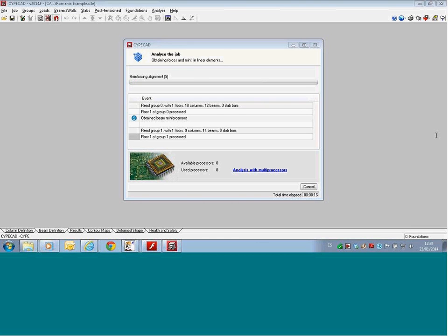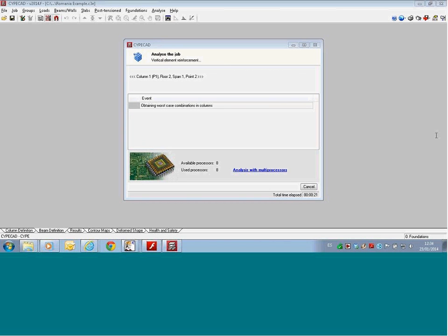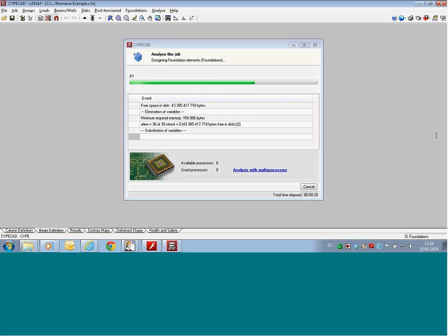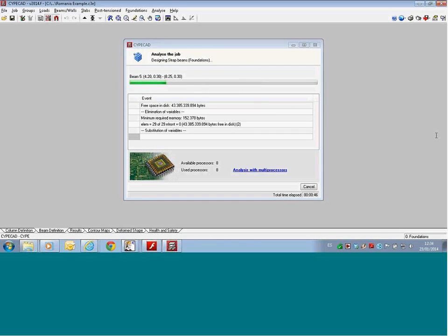That means we don't know 100% sure what the final shape of the building will be. Then for us, it's not necessary to have the analysis for the foundation. But once we know for sure that this project is not going to change, and we have the final shape of the building, then we can do the analysis of the foundation independently or with all the structure, with the foundation as well. This is an option with which we can save time.